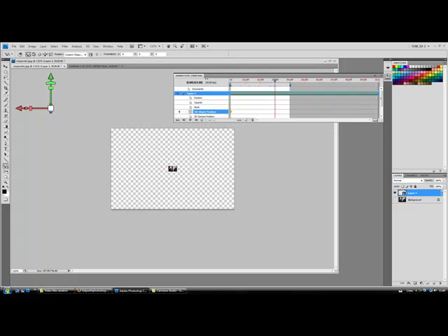Okay, while we're on that 3-second mark, I'm going to set a value in this Z orientation. Now, to be able to see these orientation values, you need to be on one of your 3D manipulation tools. So we want to rotate this on its Z axis.